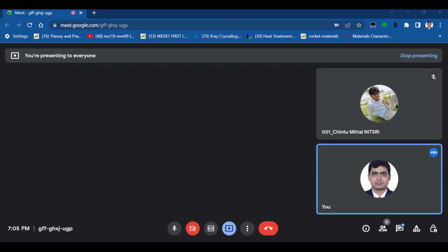Wherever tau xy is 0, that is your principal stress. This one is sigma 2 or sigma minimum, and the value of this radius is your tau max, the maximum shear stress. So from here you can already see this relation: sigma max minus sigma minimum divided by 2. That means this radius is your tau max.